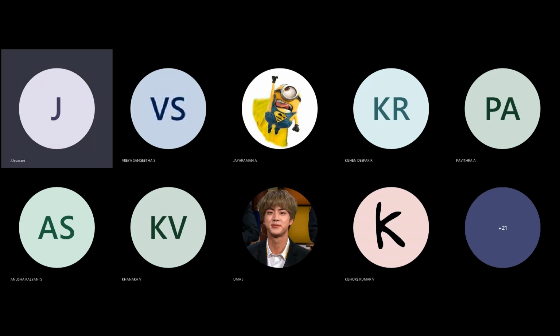Then, the multi-product concept using multi-shot and two-shot injection molding machines is used to produce soft handle inserts, multicolor parts, products with molded seals, and parts requiring flexible hinges, and assemblies with movable components.